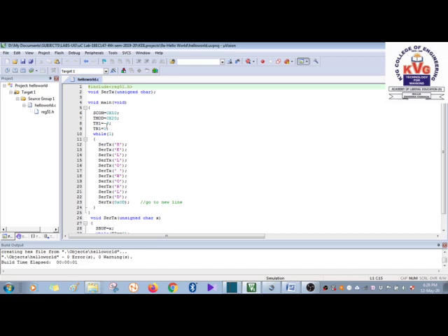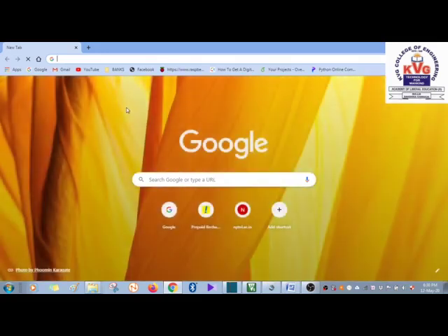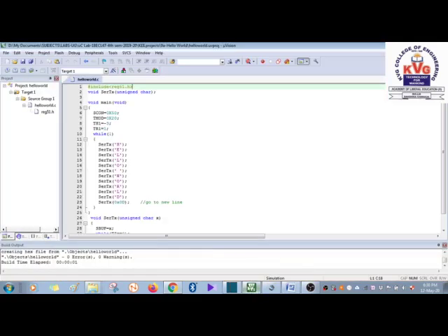And today if you write it for the 8051 and tomorrow you want to run the same program on a different microcontroller, you just have to again include this header file. It will take care. All the addresses of the registers will change if you run this program on a different microcontroller. You don't have to know all the addresses.